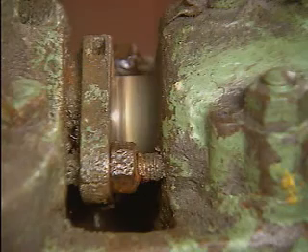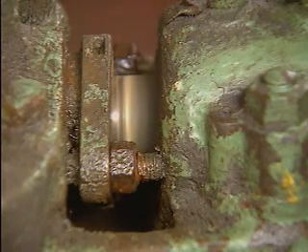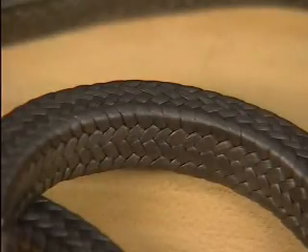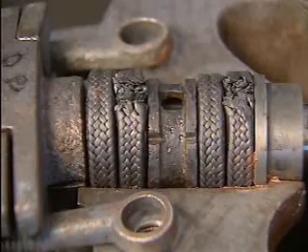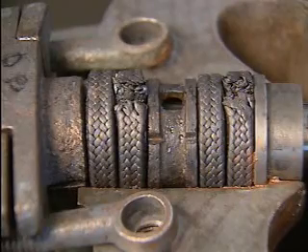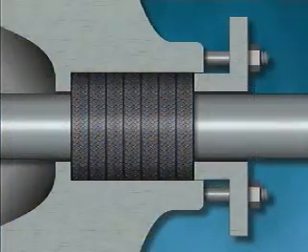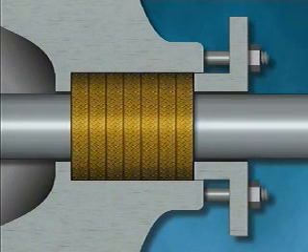One way to control leakage around movable parts of equipment, such as pump shafts and valve stems, is to use packing. Packing is generally made of tough fibers that are woven together or pre-formed with other substances into a rope-like material. Packing is typically contained in an assembly called a packing gland. This is an example of a packing gland.